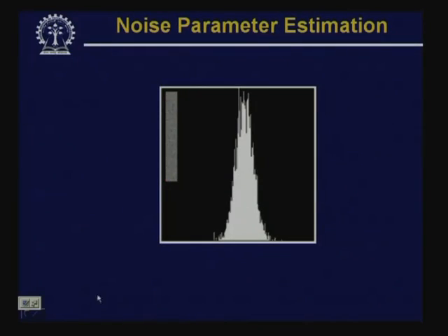Then we can go for a very simple approach. Once I know the frequency components, I can go for band pass filtering just to remove that part of the coefficients from the Fourier transform. Whatever remainder Fourier coefficients we have, if we go for the inverse Fourier transformation of that, we will get the reconstructed image. So, as has been shown here.